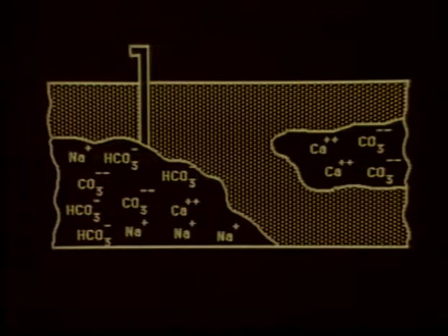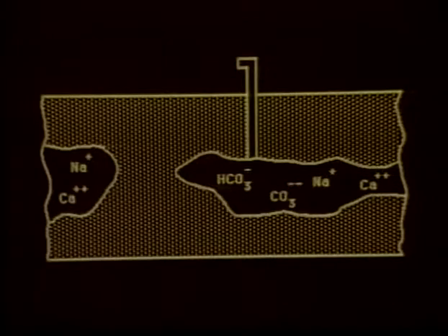Another groundwater source is from a well drilled into a formation of sodium bicarbonate. The predominant ions in this source are sodium and bicarbonate with smaller quantities of carbonate ions. These sources are commonly called soda wells and are usually located at a greater depth than limestone aquifers. The third type generally comes from strata which have very few available ions, mainly from strata deeper than sandy type aquifers, and few ions are present in these wells.